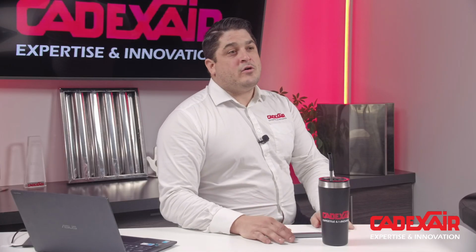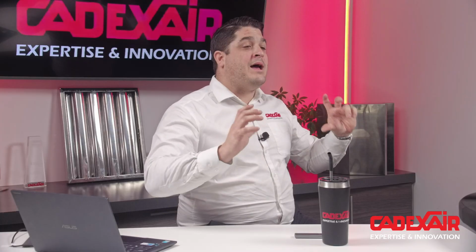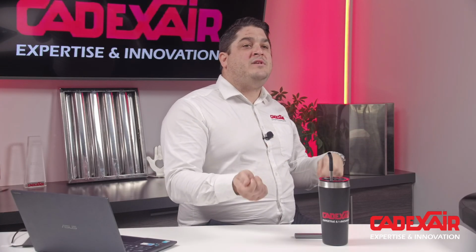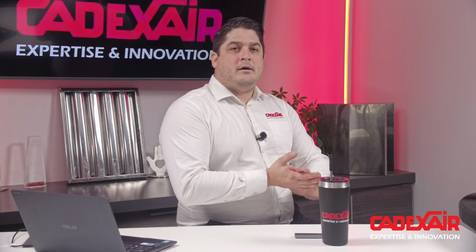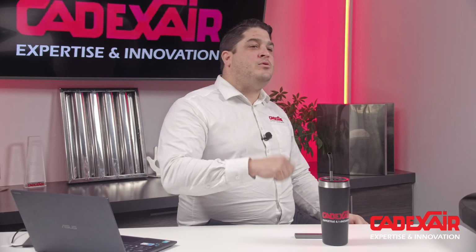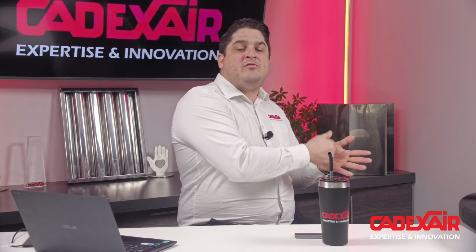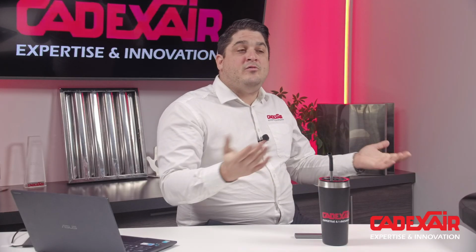So in that particular case, what we have done, we put what we call a UPS, so it's like a battery backup. What we need to understand is, when they have a generator, they have to test it every, I would say, month or 2 months. When they test it, they really cut the power. So when they change the power from the main power line from the electrical company to the generator, our PLC will lose power for a few seconds.